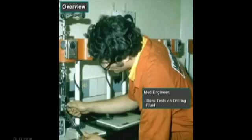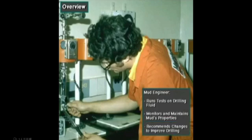An important member of the drilling team is the mud engineer. The mud engineer runs tests on the drilling fluid. The mud engineer's job is to monitor and maintain the mud's properties to the specifications of the well operator. He may also recommend changes to improve drilling, such as adding more caustic soda to increase the mud's pH.